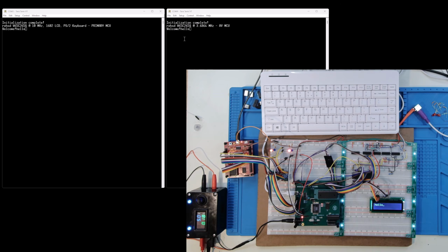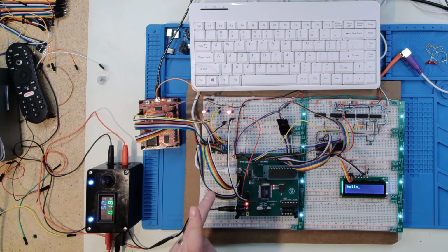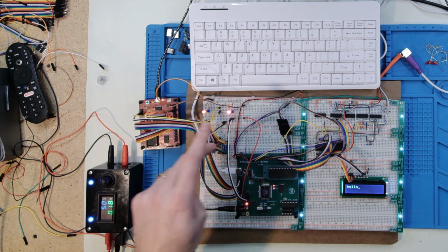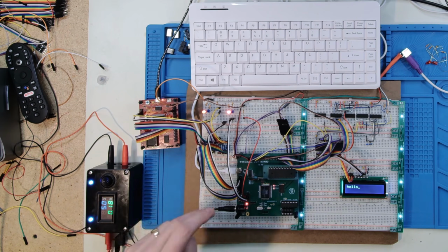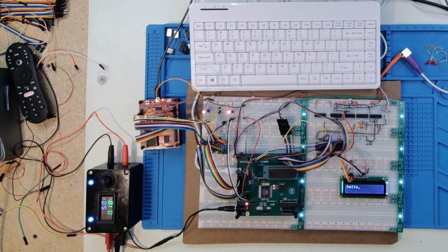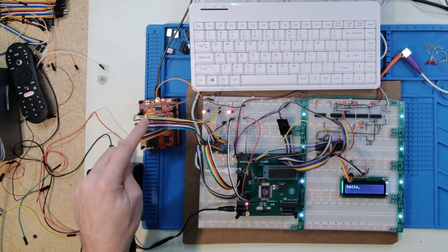So obviously, instead of sending an ASCII character code, I could send a command followed by some parameter data, whatever it is I want to do, but I've got this private connection. And I'm using these ports here. So I've got my port 5, which just comes down here, goes through the resistors over to port 5. Port 4, same thing, down to some resistors on the breadboard over to the other board. I have some debug LEDs. That's these black and white pair of wires going to the LEDs.